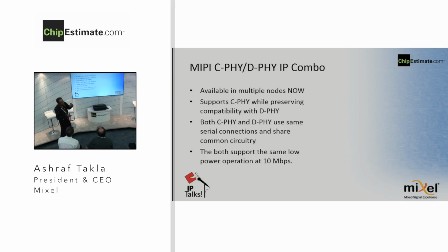One of the PHYs I mentioned is the C-PHY. The C-PHY is the newest PHY in the MIPI Alliance, and basically the clock is embedded, so you don't waste a lane for the clock. On the other hand, it is not your classical embedded clock, so I'll mention more about the C-PHY in the next slide. Basically, this is a combo IP that we have that has both the C-PHY and the D-PHY.